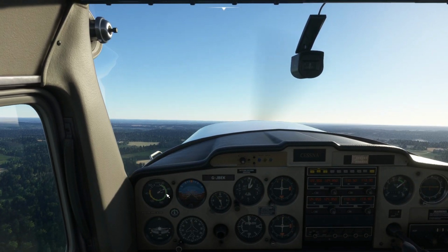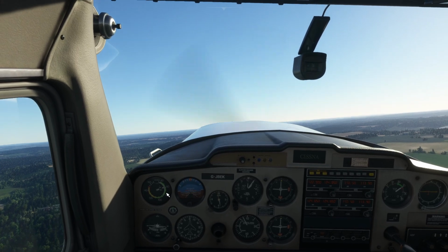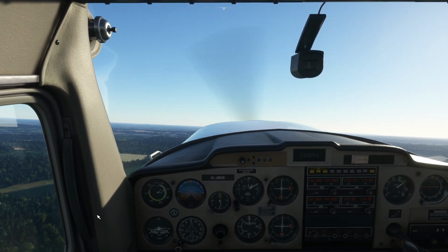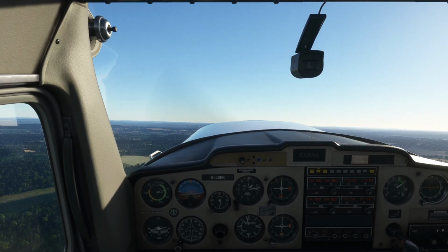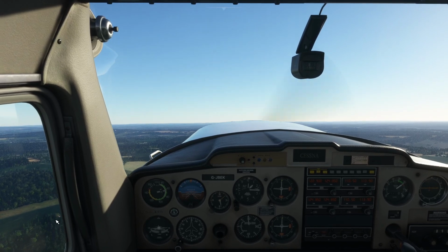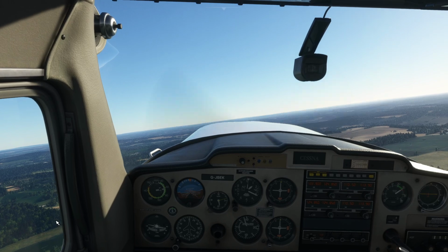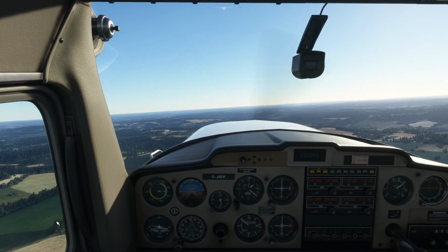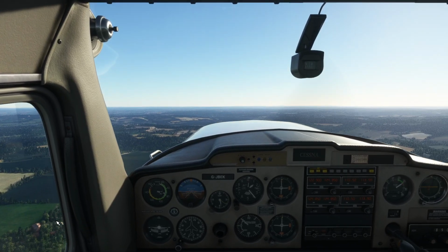We're going a bit slow, so we're going to drop the nose gently just to recover some of that airspeed. There's quite a bit of turbulence. I guess it's some of these copses of trees chuck the wind in the air. The ground isn't flat around here by any means as well. There's several valleys that will channel the air, I guess. Going a bit too far to the left, so it's very easy for the aeroplane to weathercock into the wind, so you have to be mindful of that the whole time, really.